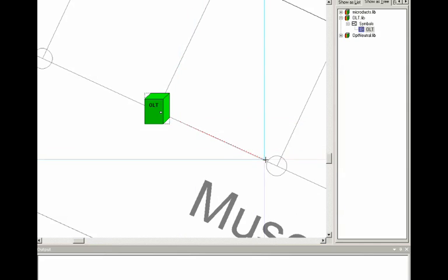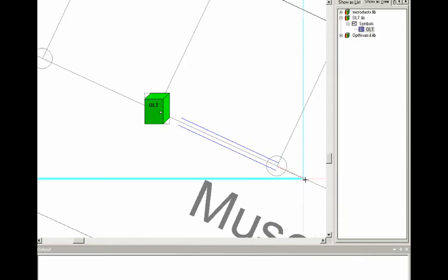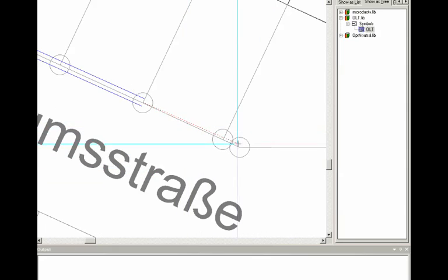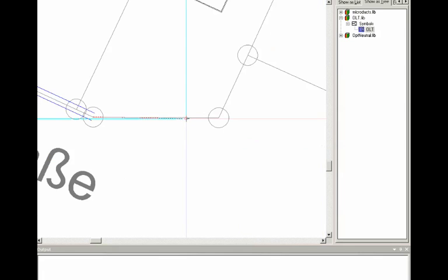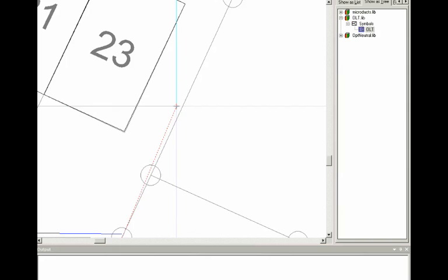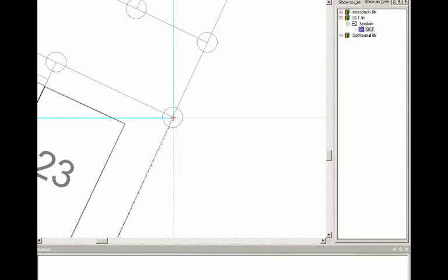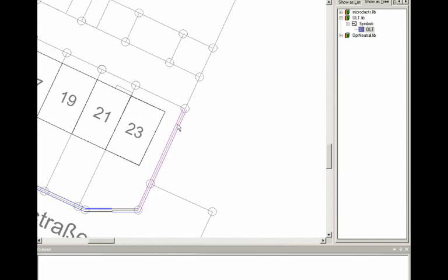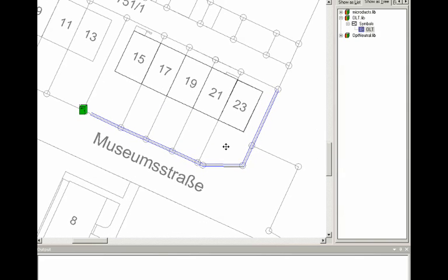Now, of course, if you have a suitable DXF map, you could just import this boundary line using the live import, which would then generate the trench automatically. But to show the ease of the manual use of AND, we're just going to do it by hand. Now that the trench is placed, it can be connected to the OLT.